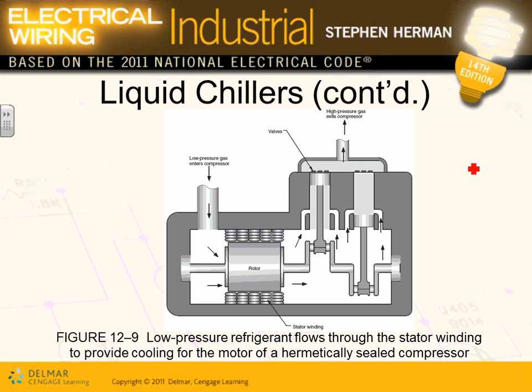The reason why they can abuse them, I don't know if you guys can see, is they take the low pressure gas and pass it right over the rotor of the machine. By passing it over the rotor, it cools it as it goes out. So they design it in a way that the motor is cooled by the refrigerant. So who cares? You can abuse it more. It can work harder. That's why the code treats it differently than any other motor. The motors that drive the chiller, guys, are treated differently than other motors because they're cooled. A fan up there is not cooled, is it? There's no coolant in it. They use a refrigerant to cool the motor as part of the process of cooling the building.